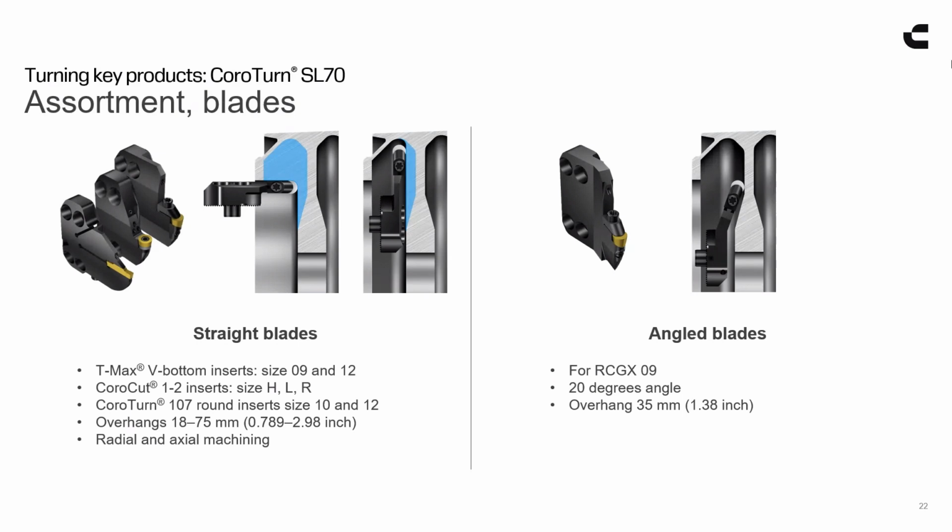So not just going in at 0 degrees to the axis of the part spun on the main spindle or radially at 90 degrees, but you can leverage the built-in design of the angle of the holder. Hopefully you can see my cursor moving to get underneath a turn pocket, or to utilize the B axis to its fullest extent, and do an index motion at any angle.